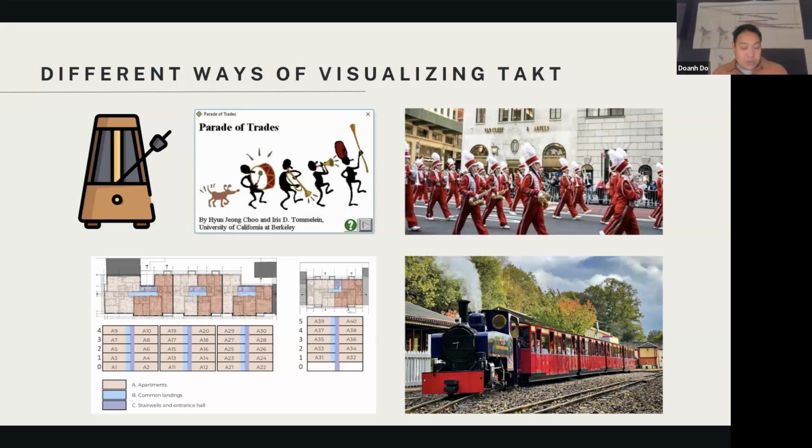When the trades finish their 1 day or 3 day takt and they need to change over, and someone's not doing the work, not able to finish on time, or there's a QA issue, you're going to see it right away. So with lean, we're always saying that if we're failing, we want to fail early, fail fast, and see it. And it has to be visual that we're failing. So seeing the waste and the mistakes is not a bad thing, because in the past, they've always existed. You just were not aware that they existed, or they were invisible to you. So that's the disadvantage of takt.